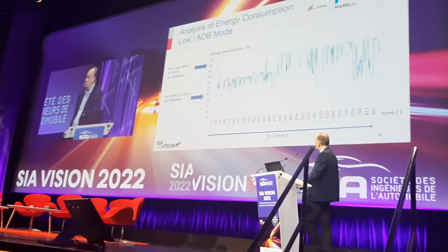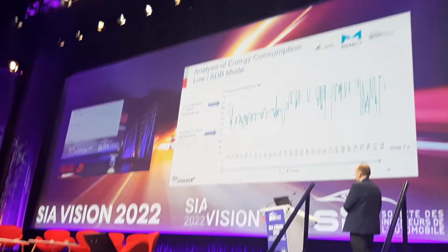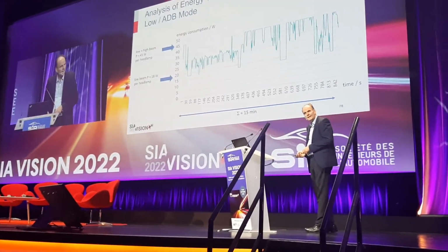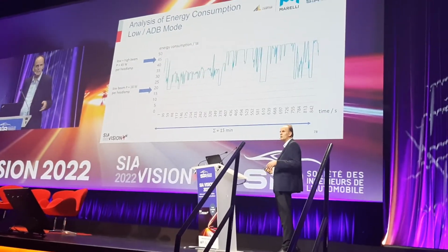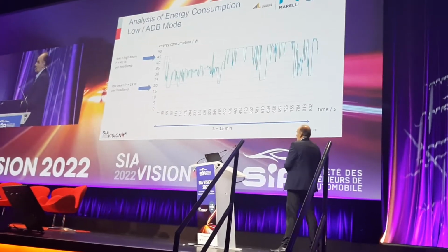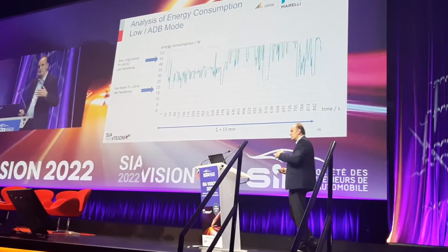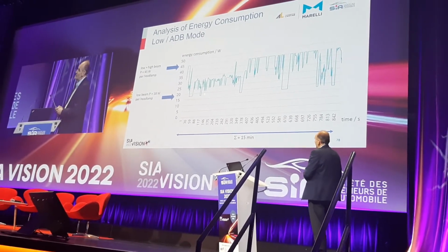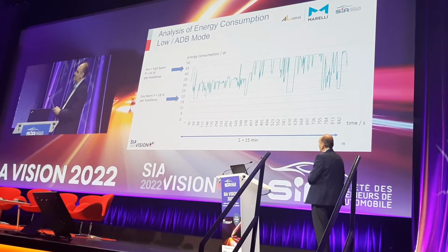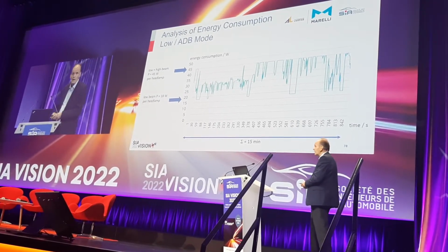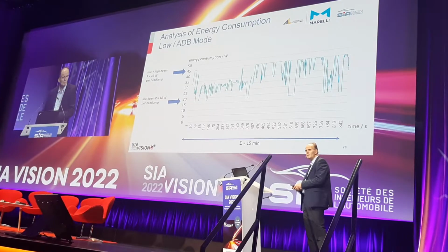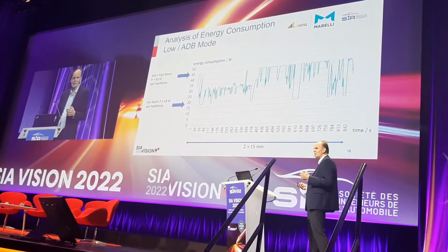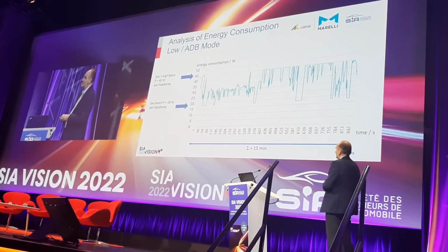When we now take the same driving section using an ADB system, we see a different picture. We see again the same low beam with 18 watt, and we see 45 watt for the ADB when it is in a full high beam situation, all segments switched on. So the efficiency of the segmented high beam is not as good as for the standalone high beam. But we also see that in the section where, in the graph before with automatic high beam switching, no high beam was possible, segments are switched on. This 70% switching on time of the ADB is realized in this system.